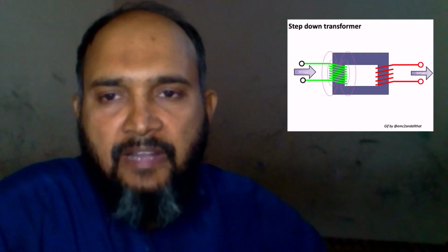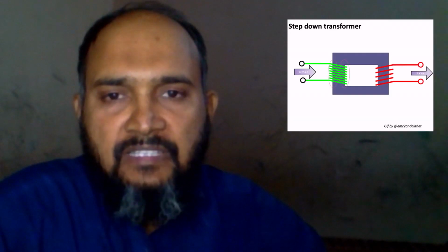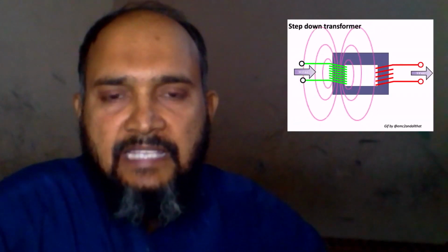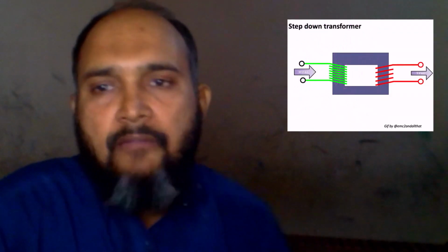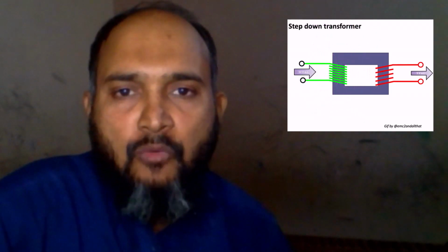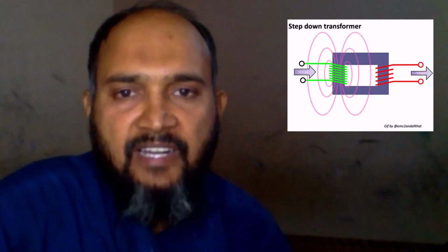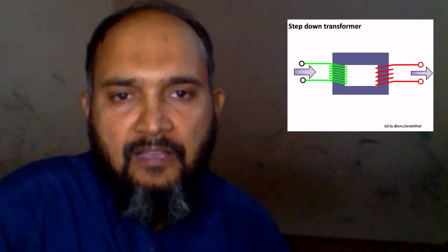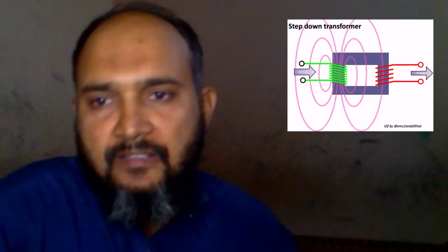The transformer's ability to step AC voltage up or down with ease gives AC an advantage unmatched by DC in the realm of power distribution, as shown in the figure below. When transmitting electrical power over long distances, it is far more efficient to do so with stepped-up voltage and stepped-down current, allowing smaller diameter wire with less resistive power loss. Then step the voltage back down and current back up for industry, business, or consumer use.